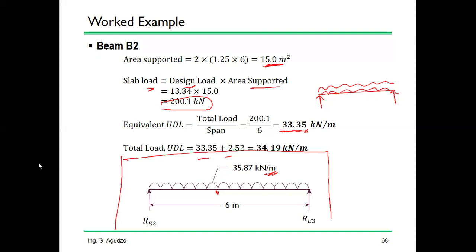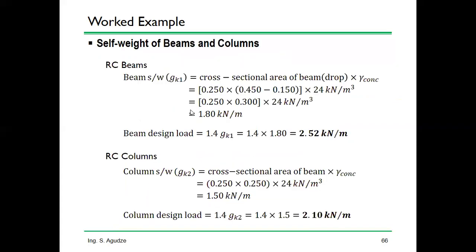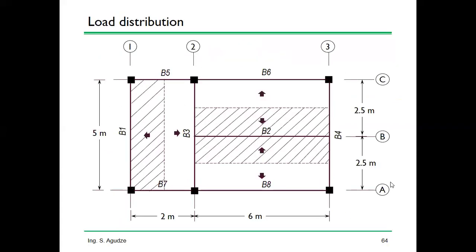Okay. So in this case, if I go to this beam, this is what we had. The total load on this beam is 215.22. This is a secondary beam, so if I divide this load into 2, half goes here and half goes here. If I take this beam, I can sketch it now like this with a support.